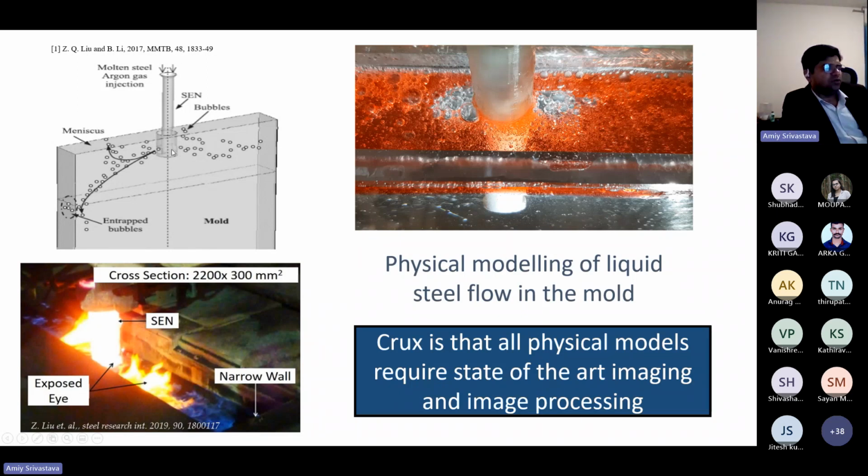So in order to avoid this clogging phenomenon, we inject argon gas. Why argon? Because argon is an inert gas and it will not react with steel. And over there, the steel is super refined, so we cannot introduce any other gas, because there is no chance of reversing that process. Suppose we inject nitrogen. In many processes, nitrogen is used as a coolant. But if we inject nitrogen over here, the nitrogen ppm of the steel will become very high. And these days customers want us to supply 50 ppm or 40 ppm nitrogen, not beyond that. So we cannot inject nitrogen.